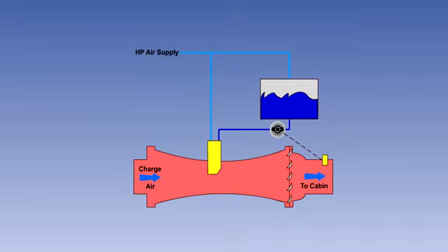The water separator does most of its work in low-altitude, humid conditions. However, at the high cruising altitudes used by modern transport aircraft, the air is very dry. When operating at high altitudes for long periods of time, it may be necessary to increase the moisture content of the conditioned air from the 1 to 2% relative humidity of the ambient air to a more comfortable level. The component used to do this is the humidifier, a typical example of which is shown here.